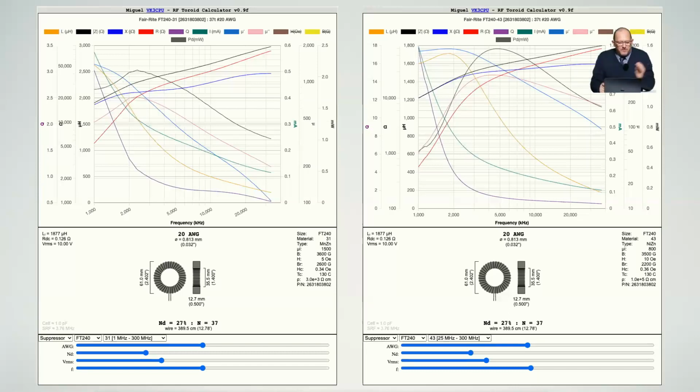I was thinking, do I do it from like 10 kilohertz to 100 megahertz? Then your resolution isn't very good. So I tended to keep it zoomed around maybe 2 orders of magnitude, and then the frequency changes the span, looking from say 10 kilohertz to 1 megahertz all the way up to 1 meg to 100 meg.